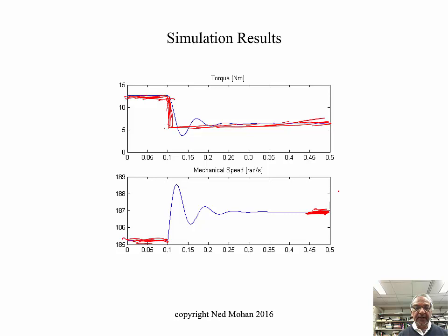And that vector control in a mathematical form, we'll see in chapter 5. In between, in chapter 4, we'll see qualitatively, or physically, I should say, maybe physically is a better word, how that control is possible, where we can keep the speed constant even when this load torque disturbance is occurring. That would be a very difficult thing to do if we had not done this D and Q axis analysis. That's really the benefit of this analysis. So let's stop here, and we continue on with chapter 4 in the next module.